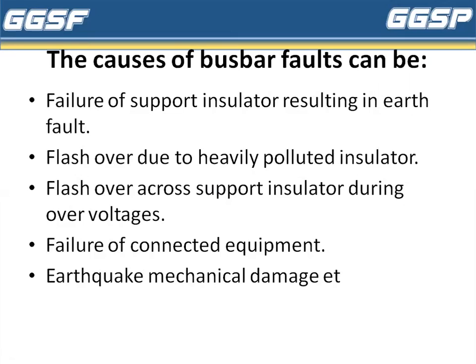The causes of busbar fault can be the failure of support insulator resulting in earth fault. Second one is flashover due to heavily polluted insulator. Third one is the flashover across the support insulator during the over voltage. Fourth, failure of connected equipment. Fifth is earthquake, mechanical damage, etc.